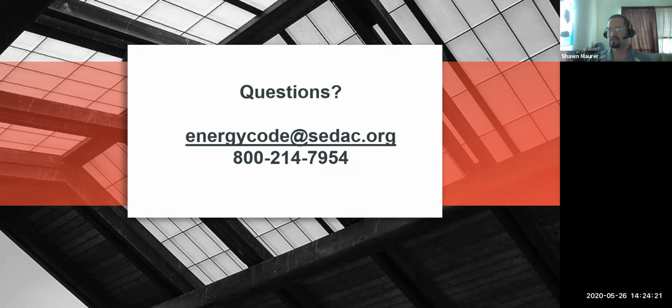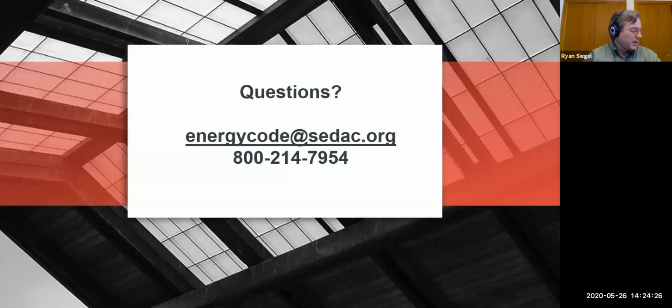Question on the lighting section, any special provisions on occupancy sensors in restaurants? As far as occupant sensing controls for restaurants, looking through the code here, the list in C405.4 of spaces that may need occupant sensing controls would be things such as enclosed offices, restrooms, and maybe other spaces 300 square feet and less, enclosed by floor to ceiling height partitions.